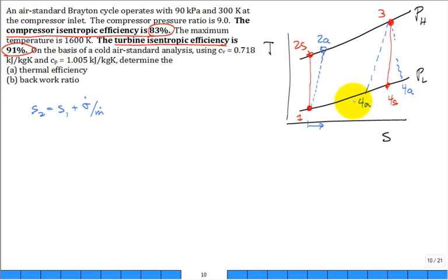All right, I think given a little bit of time, everybody figures it out that 4 actual over there, and the same entropy calculations: when you have S4 coming out after the turbine, it's the entropy coming in, plus if there's any entropy generation inside the turbine, normalized by the mass flow rate through. So there it is. Got it?